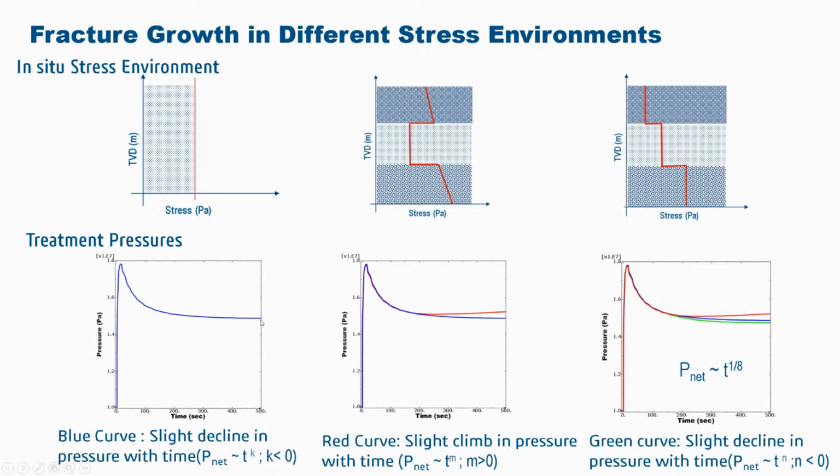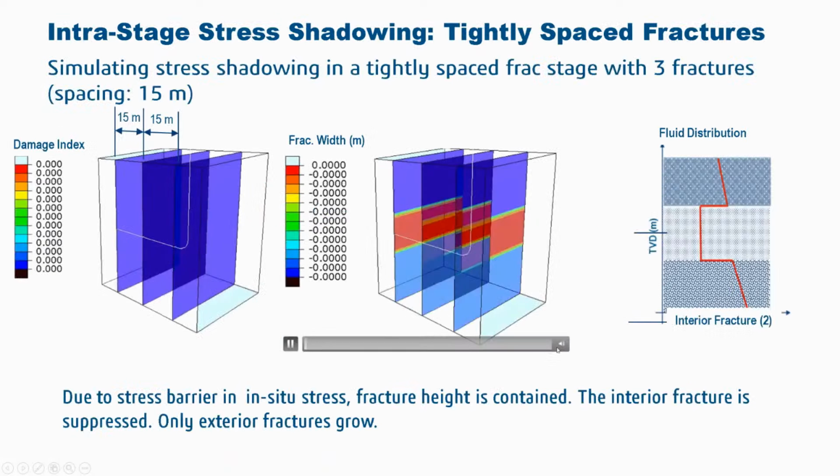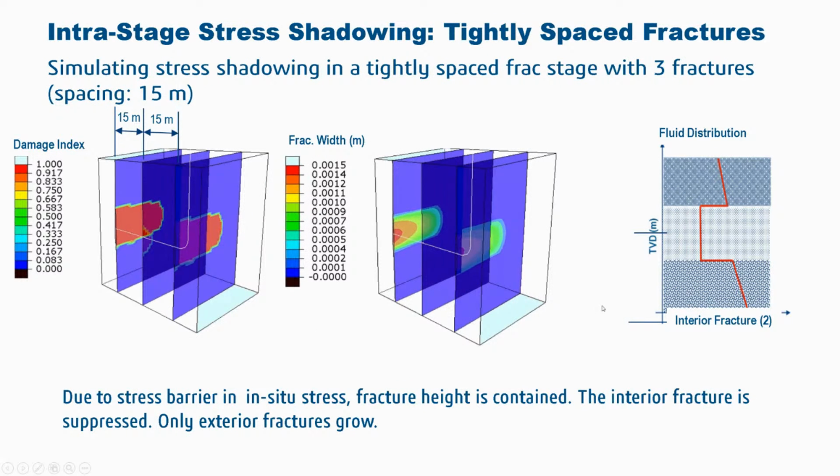And here I have shown the treatment pressure for different stress environments. So we can model multi-stage hydraulic fracturing. In many enhanced geothermal systems, you have a number of fractures that are being created simultaneously, and these fractures are used to connect the injection well with the production well.